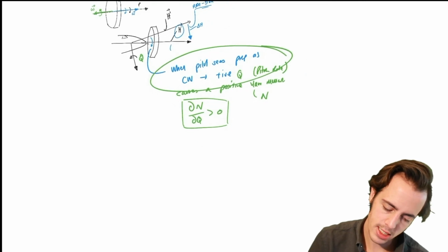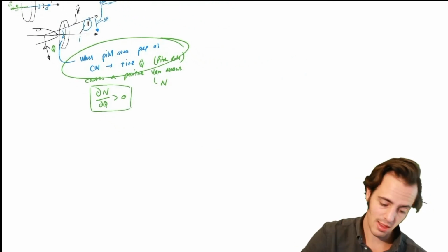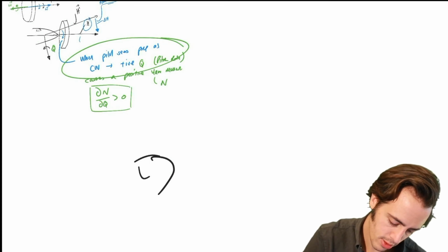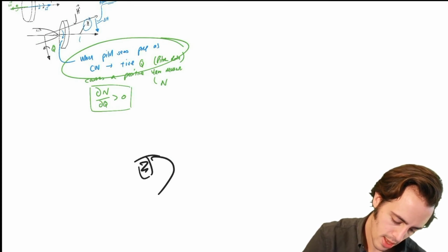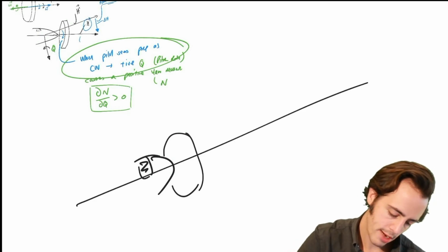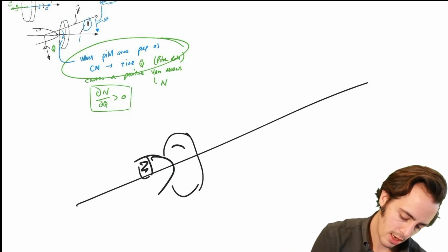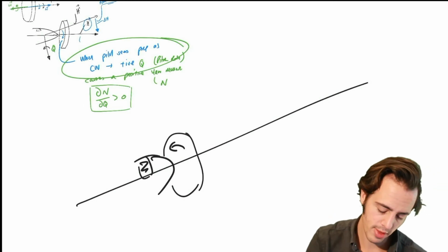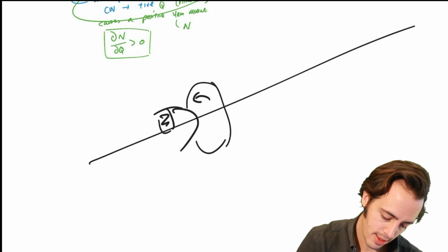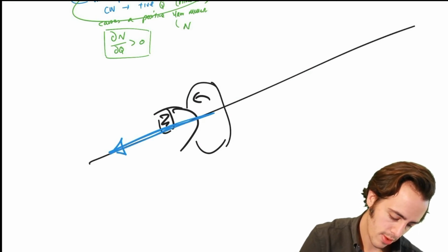Let's have a look at if we had a propeller that was spinning the other way. So we're going to draw the same aircraft here. We've got the pilot's view here, and we've got a dirty grey gyroscope on the front, which is the propeller. Aircraft longitudinal axis, and the pilot's now viewing this as counterclockwise rotating, which means that our angular momentum vector, H, is now pointing in this direction.